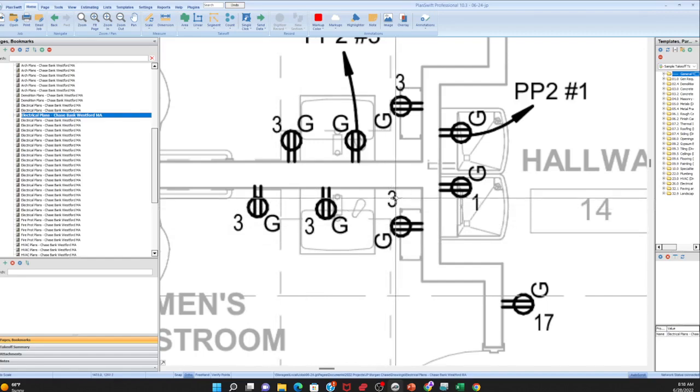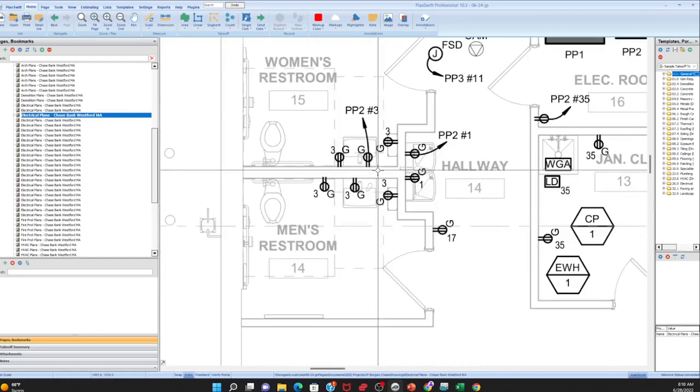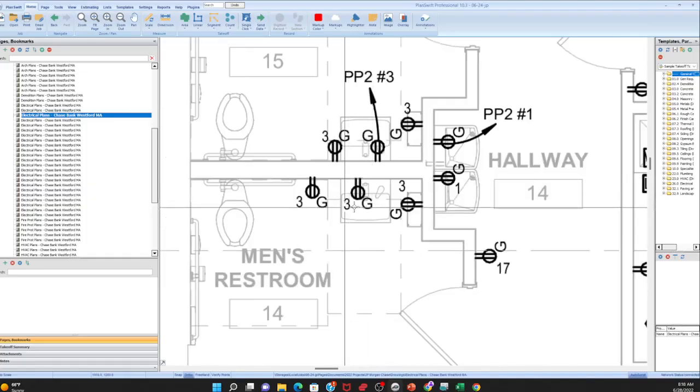Isn't that what panel schedule they go in? Right. That basically tells you what position on the panel. Yeah, these are going to... Right. So when you see that all of these are going to the same position on the panel, 3333, that means they're all daisy chained together.